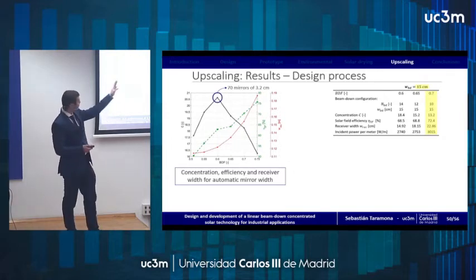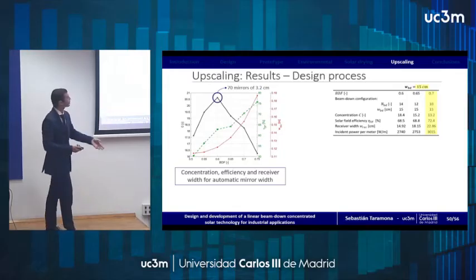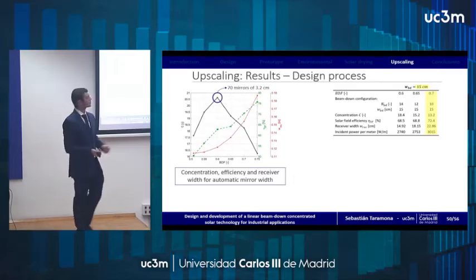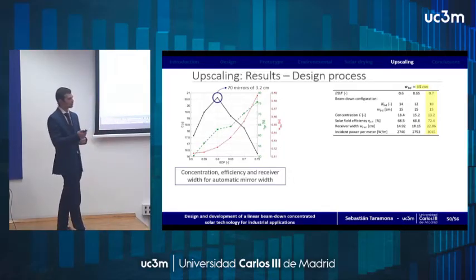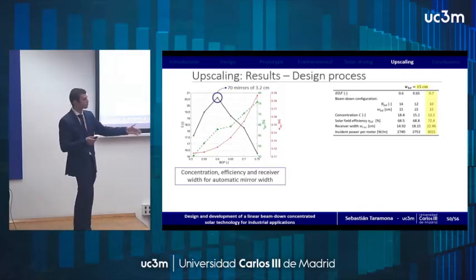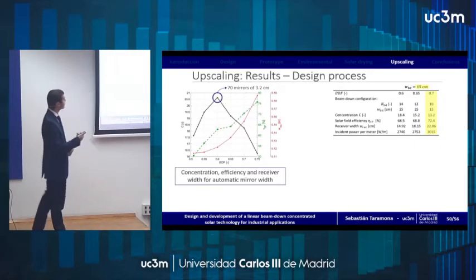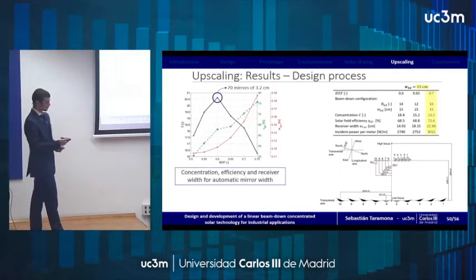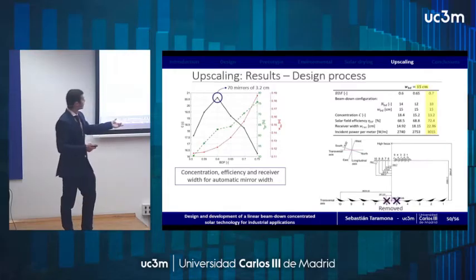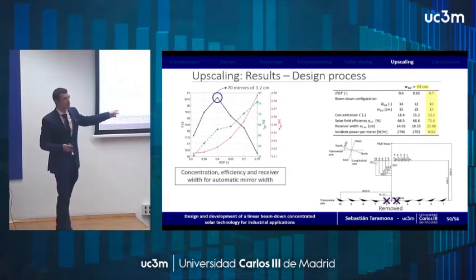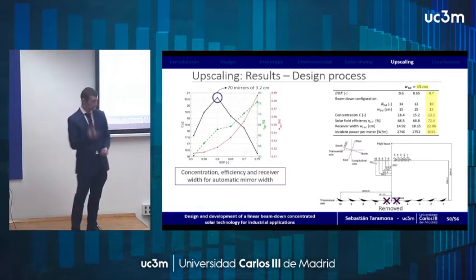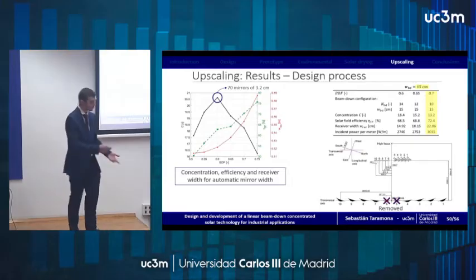And in our case, we're going to be focusing on developing the solar field for a BDF of 0.7, which means 70% of the focal height, which may not yield the best concentration, but falls in a good range between both concentration and the power we can obtain per meter length of the solar field, which is a good intermediate point. Here you can see a sketch of the solar field that we had and then modified. You can see first that the 2 mirrors in the center, we had to take away because we needed some space to first construct the beam down and then to locate the solar receiver that we're going to be using.